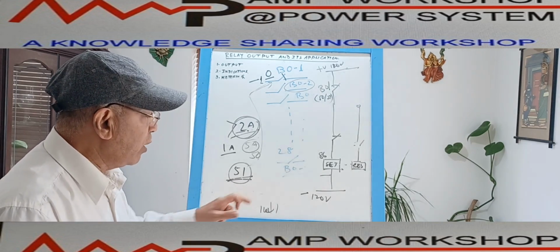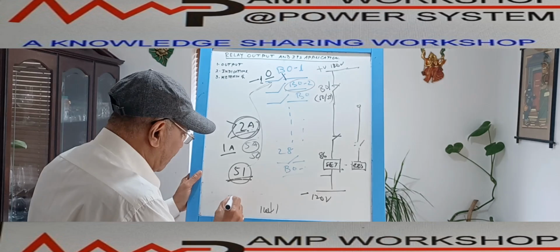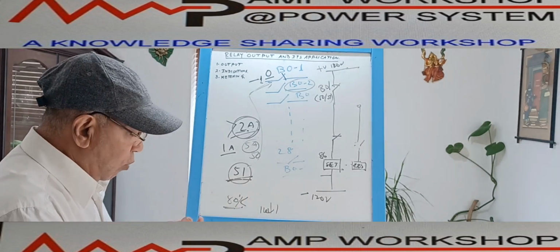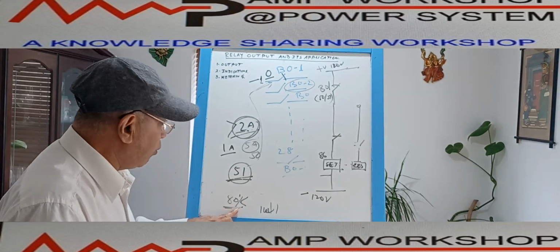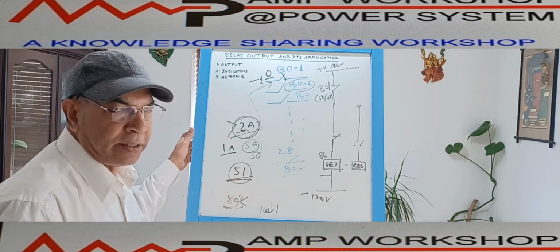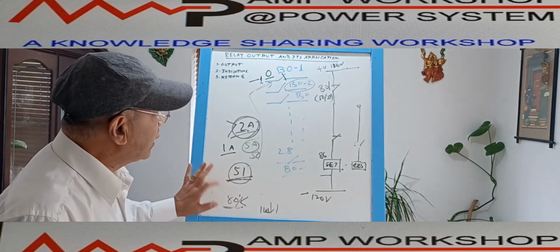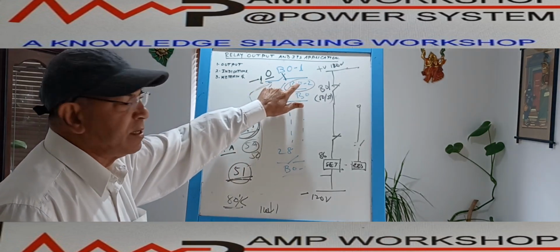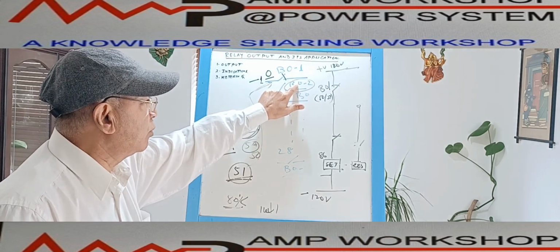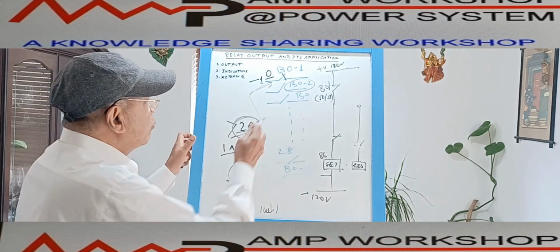This 110 volt, when it goes less than 80%, immediately it will be considered as under voltage. When this PT input voltage is less than 80%, immediately this relay will give a command. When this analog input goes below 80%, immediately it will give a command to the B02 output relay or output contact, binary output, to activate. Then immediately it will become NC.